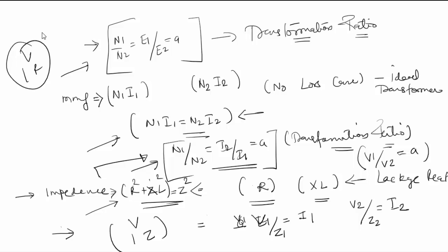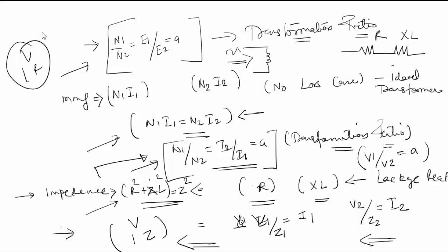If I consider the impedance at the secondary, that is the R and the XL, and want to transfer it to the primary side, then whenever I connect to a source, the primary needs to supply for the loss at the secondary, or for the R or XL present at this side also.